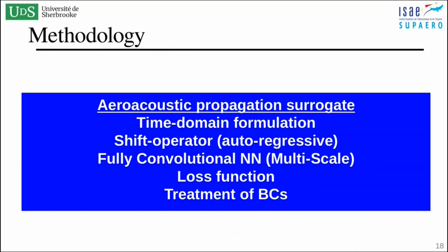So finally, let's sum up our methodology. We are going to build an acoustic propagation surrogate that's going to use a time domain formulation using a shift operator, as I showed you before, using a fully convolutional neural network in a multi-scale fashion, and this we will detail later. We will mainly also focus on the choice of loss function and on the treatment of the boundary conditions, which is a very important topic in our acoustic problems.